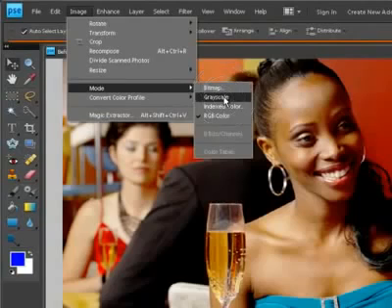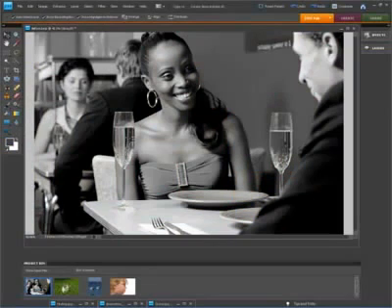When we select Grayscale, it's going to disregard all colors. Different RGB colors such as reds, greens, and blues will typically look the same in grayscale. So converting it to grayscale will give you the true effect that is needed to represent what the engraving is going to look like. Now, taking the image and adjusting the lighting is getting us probably 80 to 90% of the way there. I could engrave this as is and probably get away with a decent result. But I'm going to show you a few different tools that allow you to improve upon it even more.